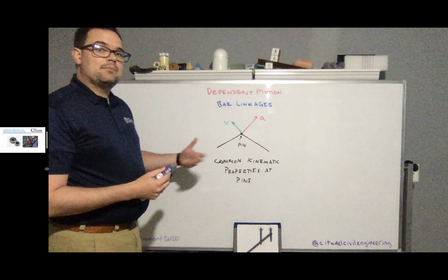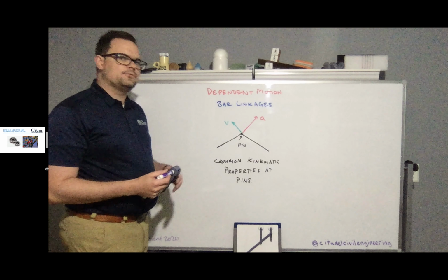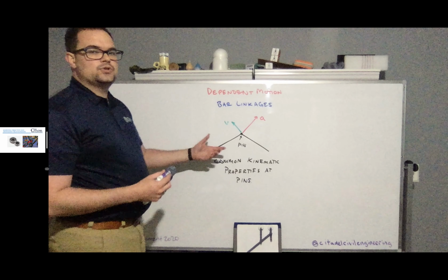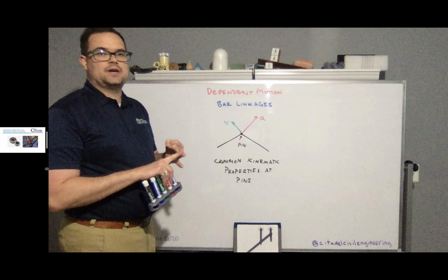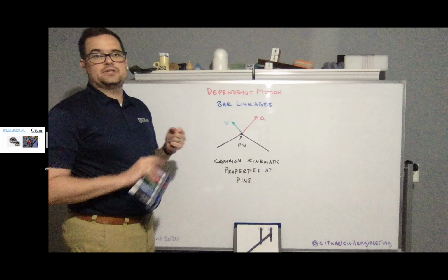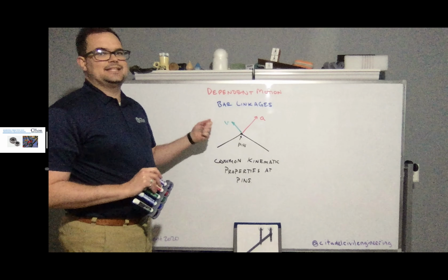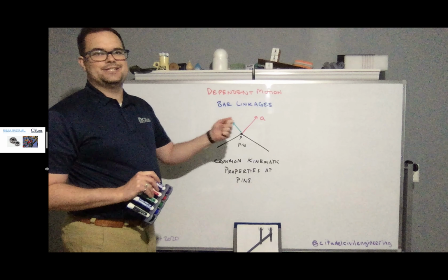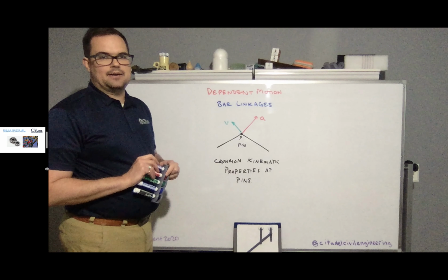We'll want to break our problems apart by pulling the pins, a little bit like frames, but we're not talking about forces anymore. Instead, we would draw our kinematic property diagrams, either fixed axis rotation, translation, or translation plus rotation for our general plane motion for each object, and know that the acceleration and velocity at each pin where they connect together has to be the same in both the diagram sets.